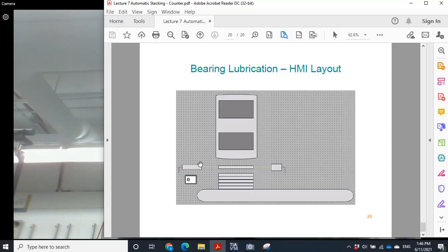The photosensor detects a beam; when the beam is cut, it means that one plate was transferred from M1 to M2, and when the number of them reaches that one, 5 in this example, then M1 stops and M2 starts.